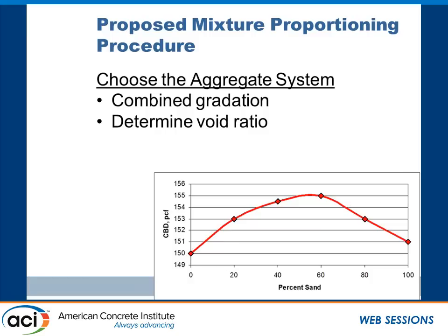So then the obvious question is, where do we want to be for our sand-stone ratio for these two materials? Duh. Somewhere around here. Why? Because rock is cheap, cement is expensive. Cement paste shrinks. All right? So we want a reasonably high amount of aggregate in the system. Do we want it in absolute maximum? Maybe not. And I'll show you why in a couple of slides. But we want it somewhere up here in this sort of region.